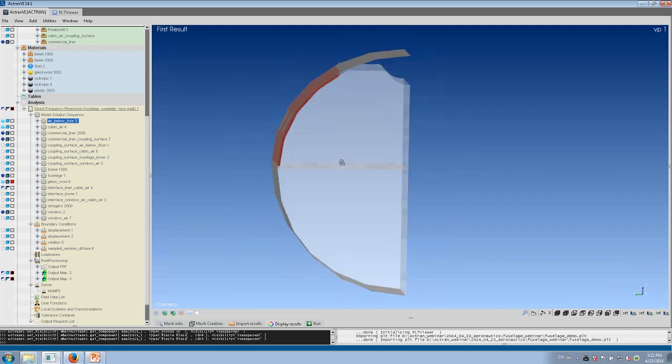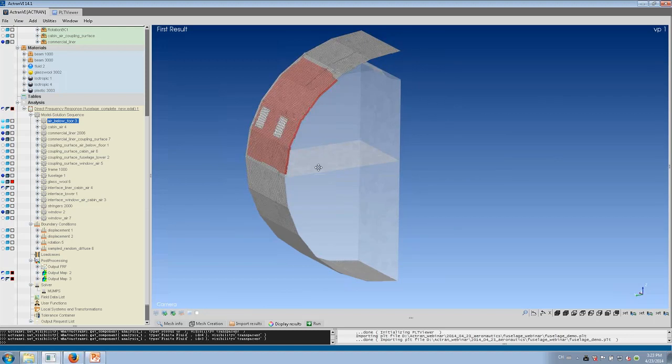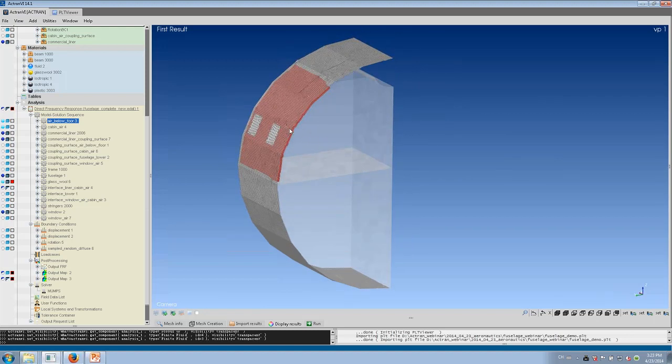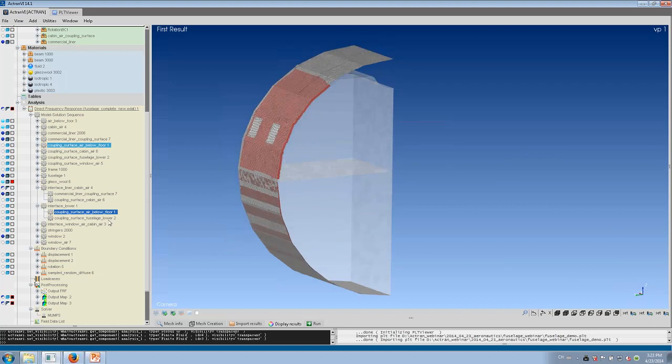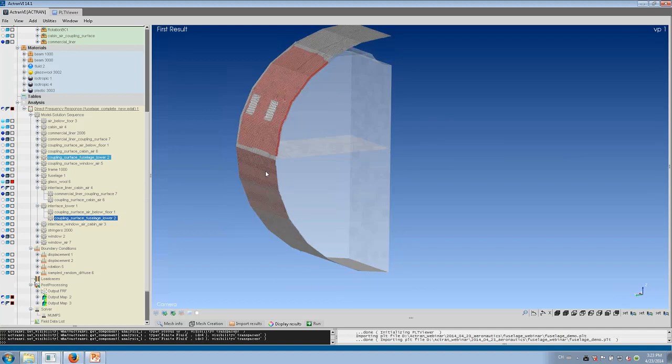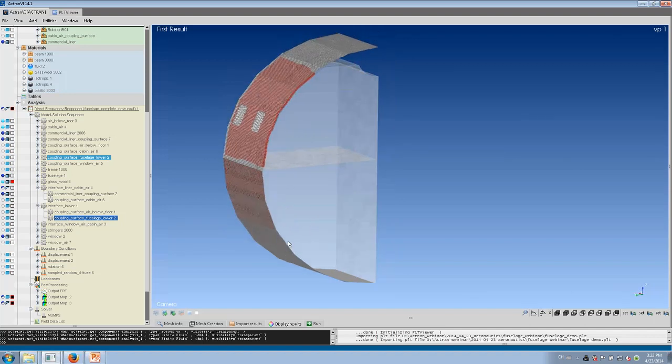Now, in Actran, the modeling is quite flexible. We can couple different parts that don't share the mesh into a global model using this interface technology. So we simply define, for example, the interface here between the fuselage and the external surface of this air domain. In this way, these two parts that are meshed independently are now connected in this model.